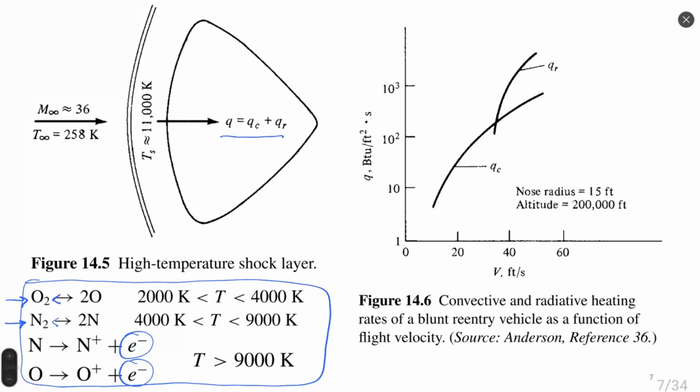So we are solving two parts for hypersonic flow: flow equations for non-isentropic transformation, and chemical processes and ionization. All these must be included inside the model of hypersonic flow. This is why the models of supersonic flow and hypersonic flow are different.